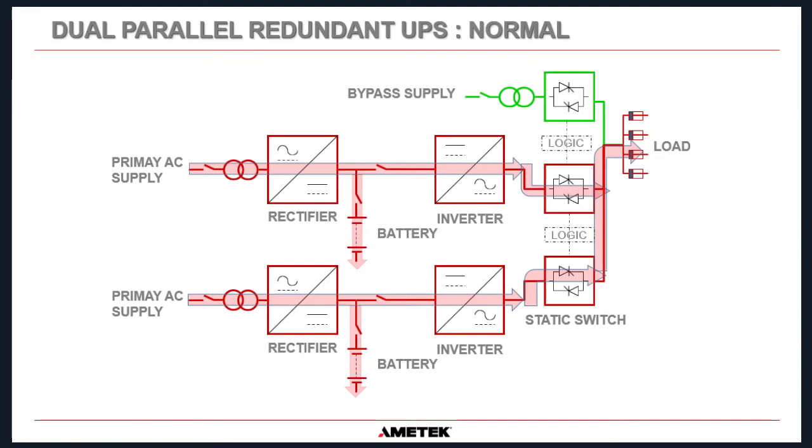And you cannot connect two different types of UPSs together. You can't connect two different manufacturers. You can't connect two different styles of UPS from the same manufacturer. They have to be identical UPSs, and they have to have the control circuitry designed in to allow them to